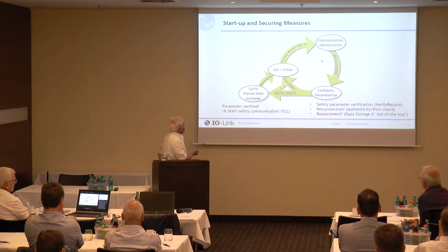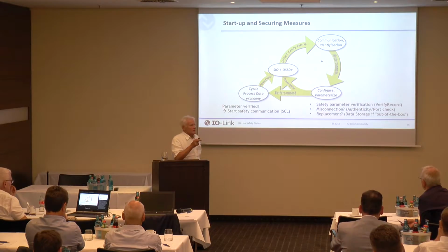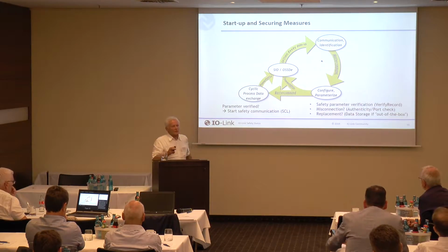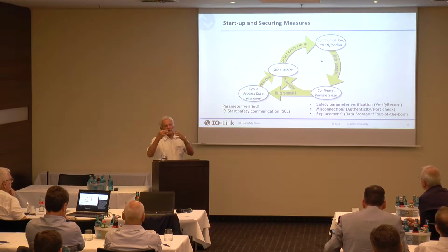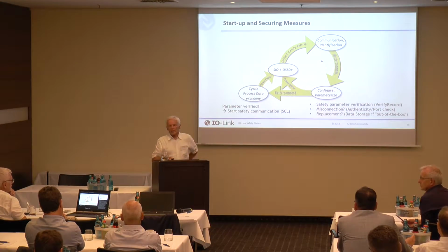Okay, this is how IO-Link works. You have this startup cycle here running from COM or SDCI. We have the wake up. In safety, we need a little bit of modification because the safety devices have a startup self-testing, and this self-testing is usually more than the 300 milliseconds that we require for IO-Link.